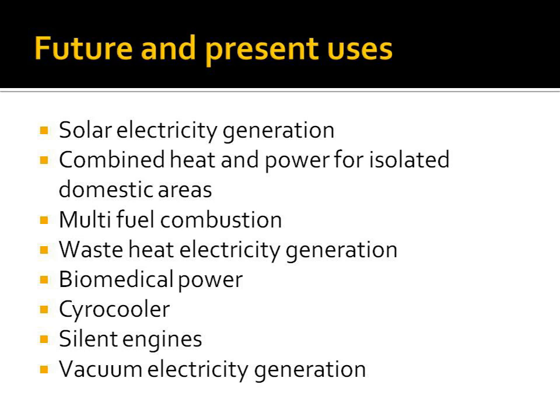Cryo coolers is a concept of working a Stirling engine in reverse by adding mechanical work to the system. The heat source, which would be the heat source if the Stirling engine was worked in the traditional way, when worked in reverse, becomes supercooled.